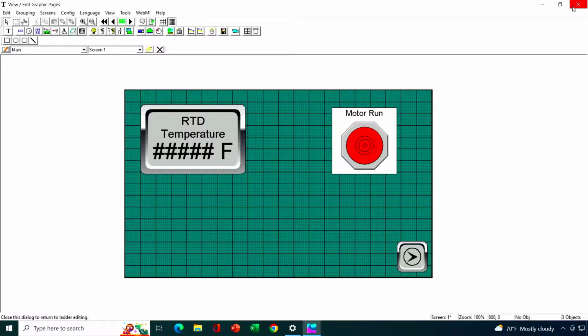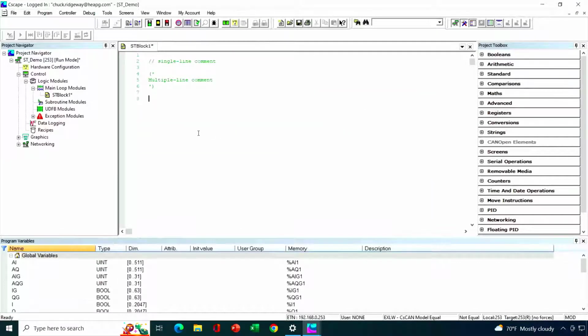But as all of you probably know by now, the values don't necessarily come in already scaled for degrees F. It depends on the module or the OCS model, but often the values come in from the analog input registers in 20th degree C increments. So we're going to want to do the math to convert the values coming in over to degrees Fahrenheit values.